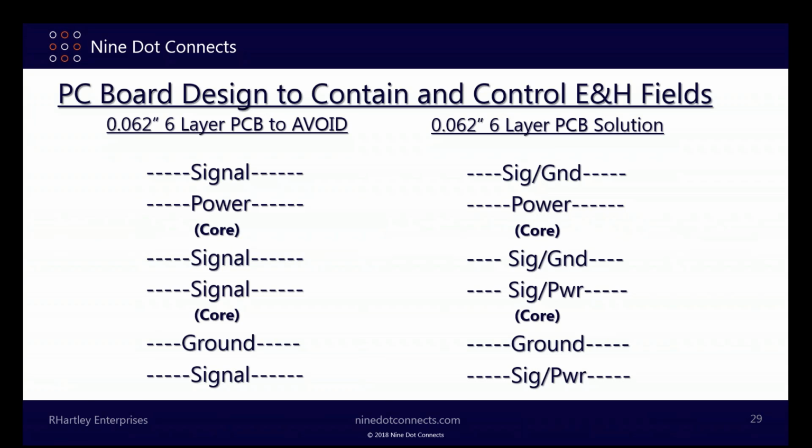Power doesn't come from one large high impedance dielectric space. It comes from a bunch of small low impedance dielectric features, all of which have tight containment of fields, all of which work well with one another. The other thing about this that's good: all of the signals now are referencing the plane directly above or below because of the way the copper pours occur. So the signals, instead of intermingling with power, are next to the power instead of being coupled with power.